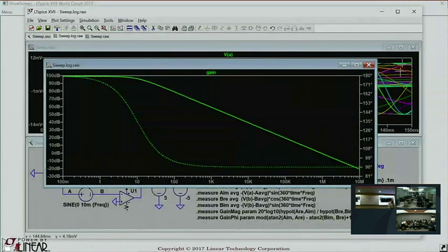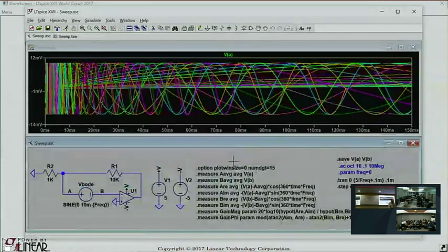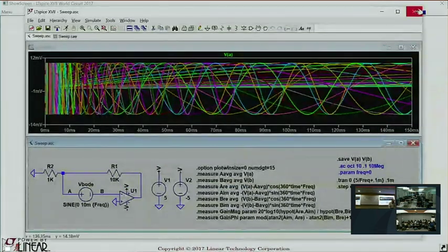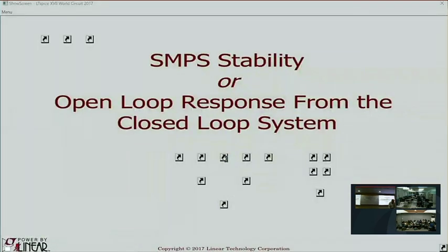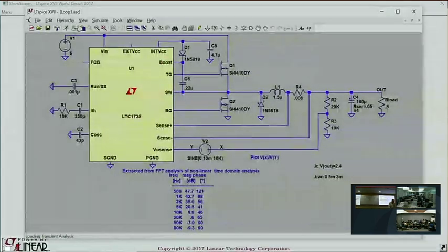Okay, great. Many people love to do this, and you can do this for a switch mode power supply, and many people like to do that, and that makes them happy, and I'm happy for them. However, I never do. I really never look at a peak current mode buck in the frequency domain, and the reason I don't is because I can't accomplish anything with it. Not only is it not particularly valid, you won't change the design when you're done.